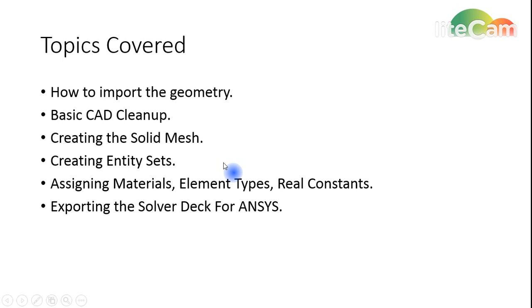Okay, these are all the things we'll be doing in this tutorial. We'll start by importing the geometry in Hypermesh, then we'll do the basic card kind of thing, and then we'll create the solid mesh for the component. Most of the tutorial will lead you up to this only, but since we'll be solving this model in